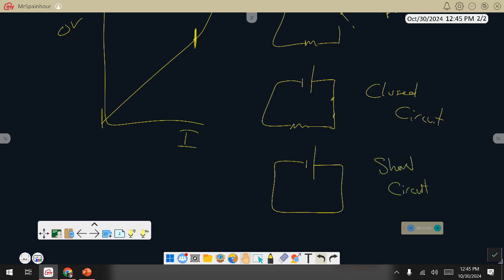The defining characteristic you can see in its picture. What's the defining characteristic of a short circuit? There's no what? There's no resistance. Why is that a problem? No resistance means, hey, electricity can flow. We're good. We're great. What's the problem? Extra current is not inherently a good thing. A lot of extra current means a lot of extra energy. And a lot of extra energy means heat.